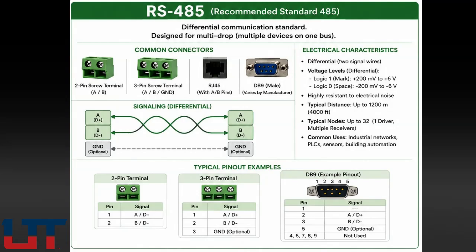RS-485 is what most people mean when they talk about Modbus RTU wiring. It supports a multi-drop bus topology, meaning you can connect up to 32 devices on a single pair of wires, and it can run up to 1,200 meters. That makes it practical for connecting a series of meters or field devices along a pipeline or process unit. It's half-duplex, meaning only one device talks at a time, and the Modbus RTU protocol is designed around that constraint. We'll talk more about protocols and how they relate to networking later.